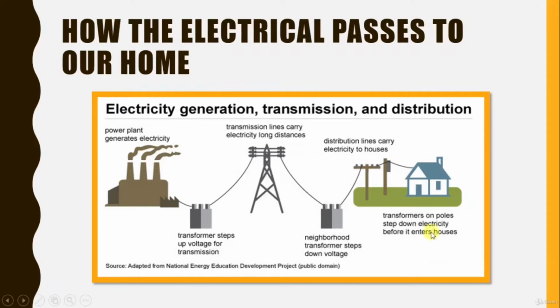The line to neutral voltage will be 220 volt or 110 volt, depending on the system. Therefore, the line to line voltage will be either 380 volt or 190 volt. By the way, line to line voltage means three phase. Line to neutral voltage means single phase.